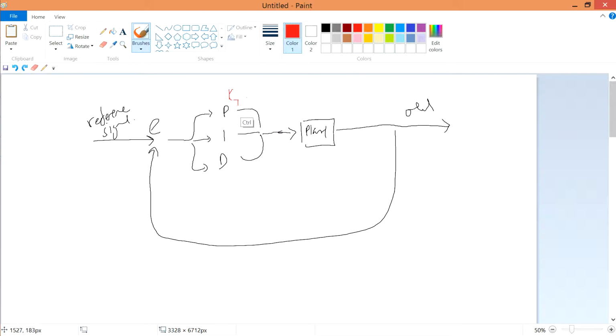This is the proportional, so it's Kp. Then we have a Ki for the integral, and we have 1 over s. We say that 1 over s is integration, while Kd s is differentiation. So why do I say 1 over s and s? For example, we have an error over here, and then we multiply by 1 over s, which equals the output Y over s. If you bring this s over to this side, we have E over s equals sY, which is also equal to dy/dt.